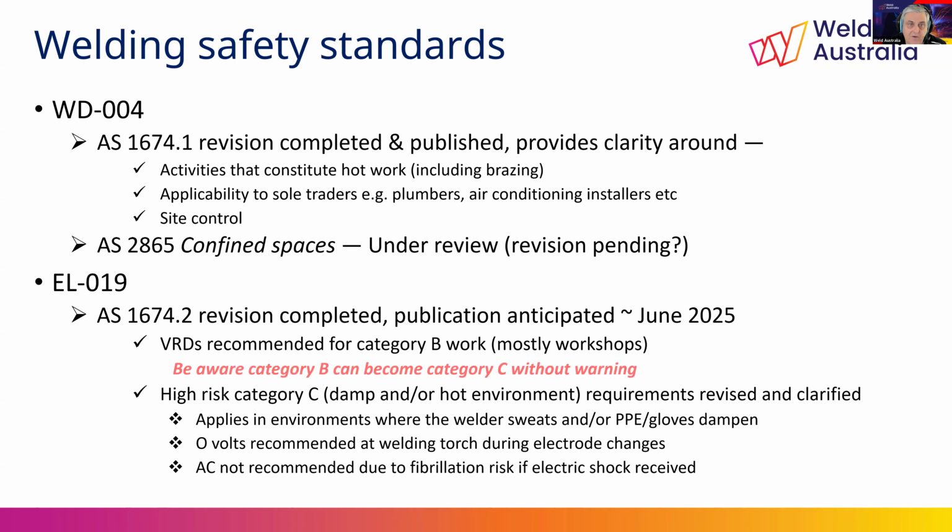Now, with AS 1674 Part 1, the revision makes it clear that hot work includes brazing, particularly when performed as part of repairs or modifications to copper piping for air conditioning, and amongst other things as well, even just using a heating torch, for example, or an air gun in some situations. This clarification is necessary as insurers typically insist that this standard is followed by persons performing hot work. And this includes contractors and sole traders such as plumbers and air conditioning installers performing hot work.